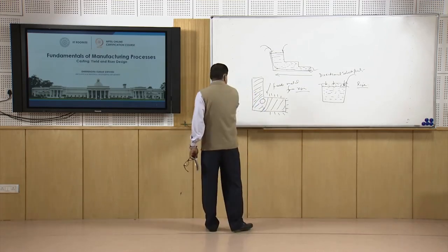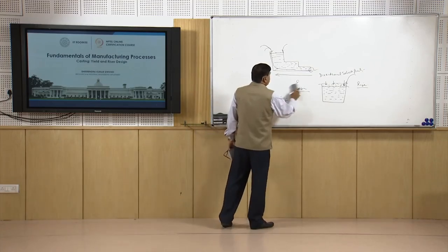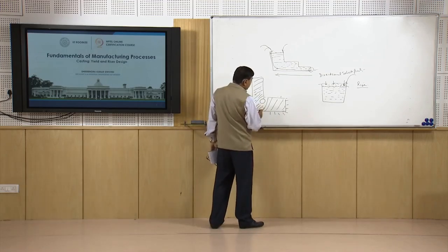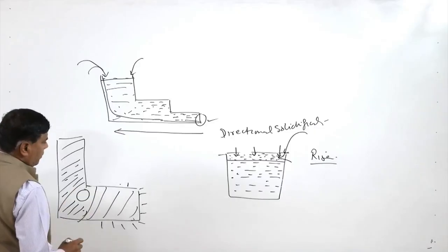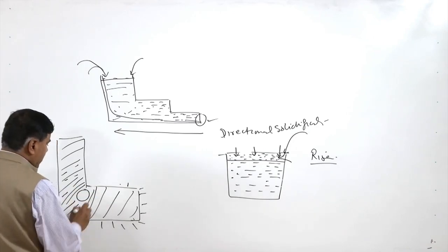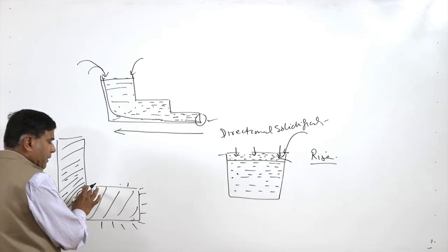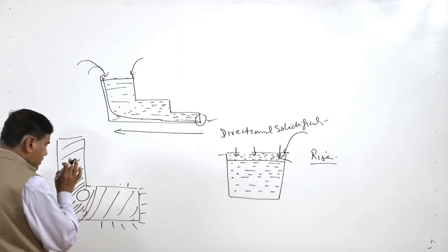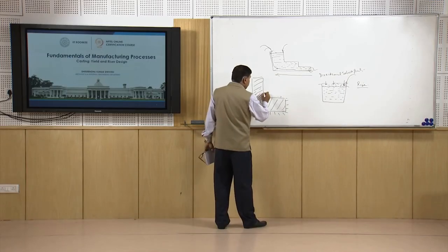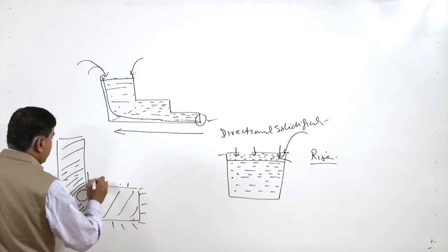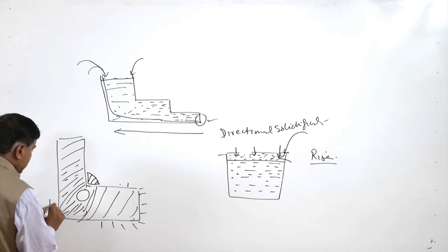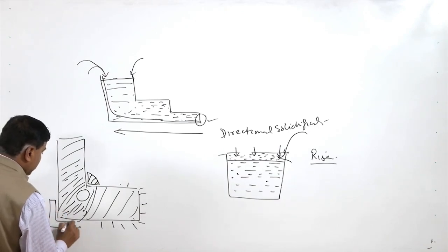Say if the hot spot is being formed at this location, since this is the area which is solidifying at the end, we will try to have this area solidify at a much faster rate, so that the hot spot is not formed here, or this region does not form the last region to solidify. For this purpose we add a metallic piece at this location.